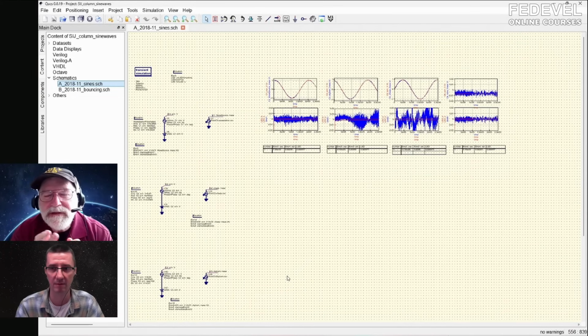Well, there are some limitations to what this can do. It does not take layout information like an ODB++ file and bring it in and generate S parameters. I don't know of any free open source tools that do that, but we can take different transmission line geometries and topologies, and simulate the waveforms that we expect to see. So very simply, we can specify dimensions of our track on our PCB, length, width, and maybe the PCB stack up. We can put it directly into this simulation software.